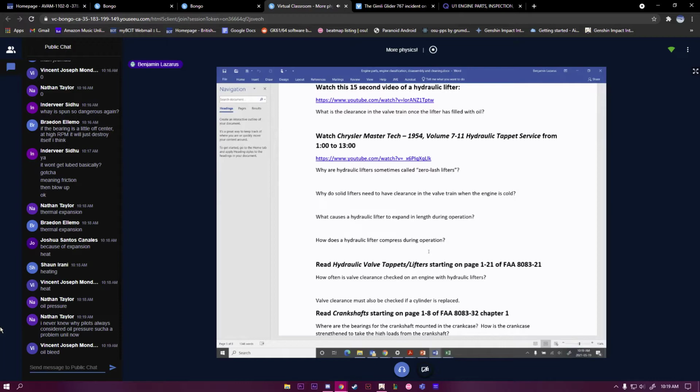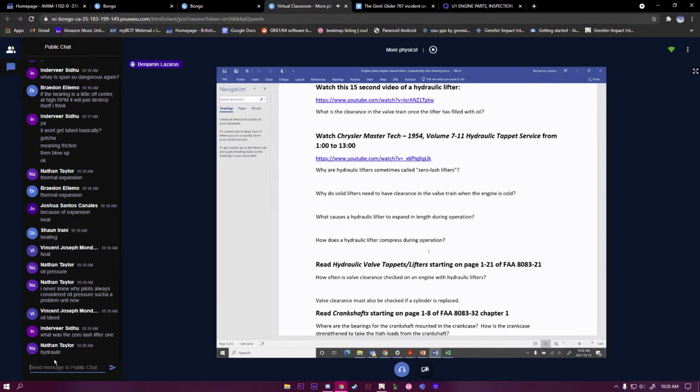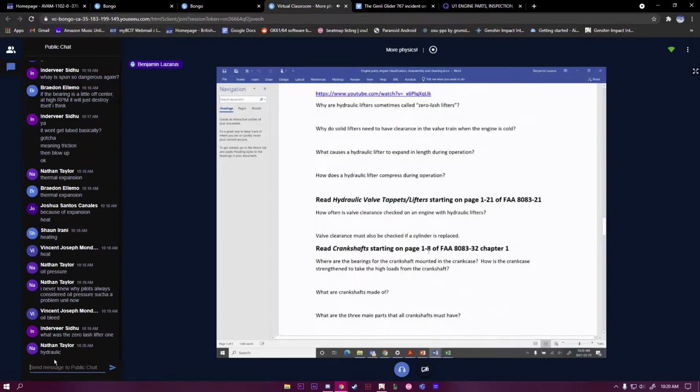In fact, I did an engine run last Wednesday, I think, when I worked, and my job sitting in the right seat was to do nothing but watch for oil pressure when we did engine light off, make sure that we had proper oil pressure. And if I didn't see oil pressure, I was going to call it, and the mechanic, my crew lead in the left seat, was going to pull the emergency stop lever and shut it down before we wrecked anything. Okay.